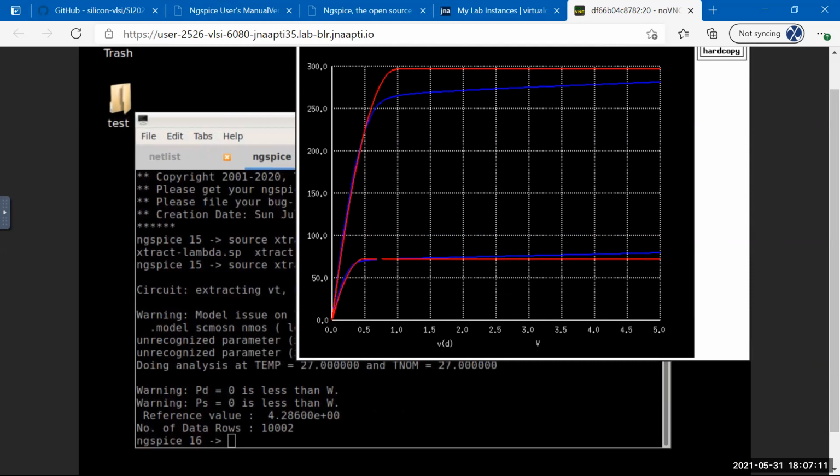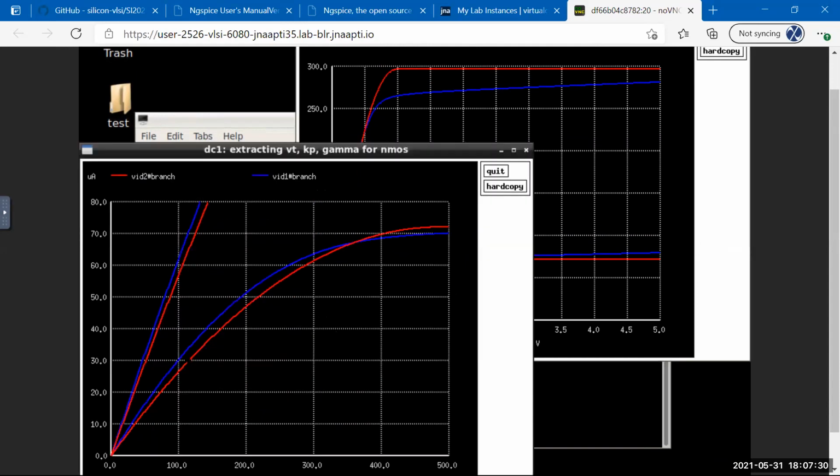So you can see for the 1 volt, it is quite close. And for 1.5 volt, it is quite different. And this we saw, as we went higher and higher in voltage, it started deviating more and more, right? So Praveen, to answer your question, you can see in the linear region there is obviously a deviation because we are missing a lot of parameters, right? We have 100 parameters in BSIM 3v1, we have 5 parameters in level 1. So there will be differences, but you can see it pretty closely matches in the linear region also.